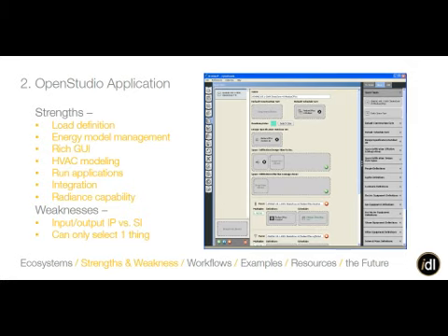Can you input a Revit model of the building? You can. There is a workflow for that, but it's really a Revit model to a gbXML export, and then you can import that into EnergyPlus or OpenStudio. It's not super smooth, but that's getting more and more developed as well. The DOE just, I think, put $2 million into a research project for gbxml.org to define some of those pathways on how you go from Revit to some of these more powerful energy analysis programs.